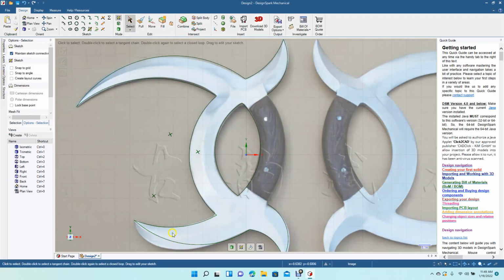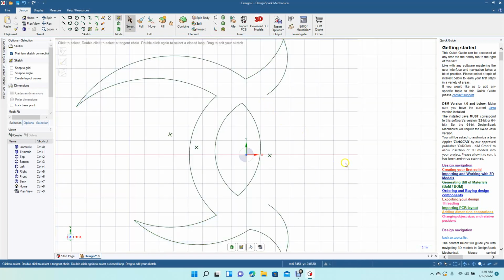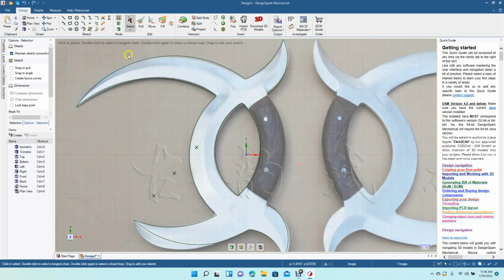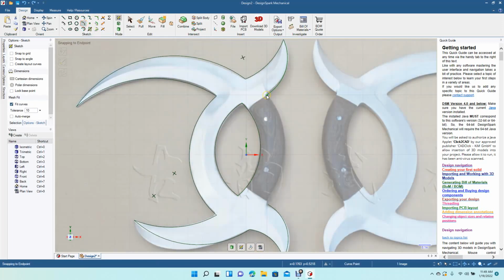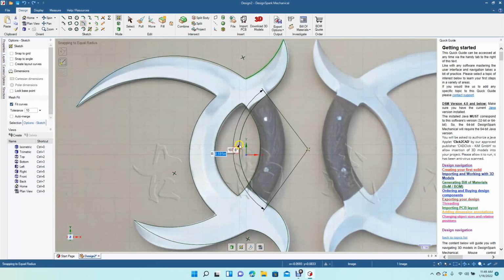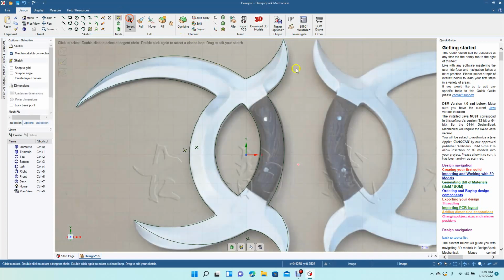Okay. We don't need this anymore, so I'm going to go ahead and delete it. Oh, actually, you know what? I did need it. I got to put that last one in there. So let's go back to the 3-point arch. We'll come from endpoint to endpoint. Then we're going to move this out. This is going to be a radius of 0.855 inches, and the degree is 67.8. Okay, now we can get rid of this.